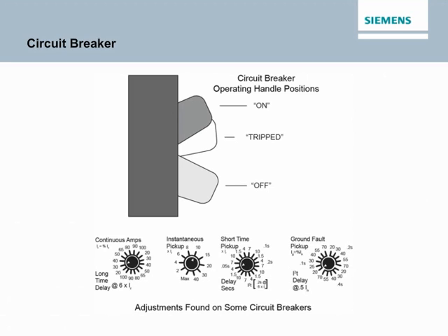However, circuit breakers have other advantages as well. For example, some circuit breakers have adjustments or a replaceable trip unit to allow the level of fault current required to trip the breaker to be set to match the application. Some circuit breakers also have communication capability to allow information to be sent to power monitoring equipment or display devices.